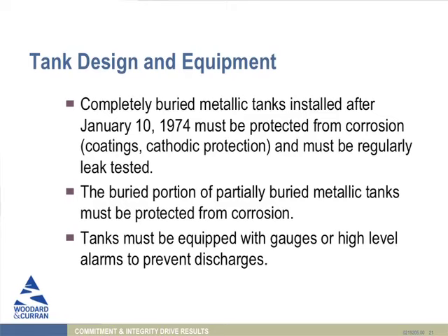Tank design and equipment. Similar to the UST rules, tanks under the federal SPCC rules have to meet certain design requirements. If you have a completely buried metallic tank, now this is metallic, not fiberglass reinforced plastic, installed after January 10th, 1974, it has to have corrosion protection and be regularly leak tested. Don't think anybody has this. It sounds like the tanks have been upgraded, but if you did have a single wall metallic tank, it has to meet these requirements. Buried portions of partially buried metallic tanks need corrosion protection for the part that's in contact with soil. And tanks have to be equipped with gauges and high-level alarms to prevent overfills and discharges.